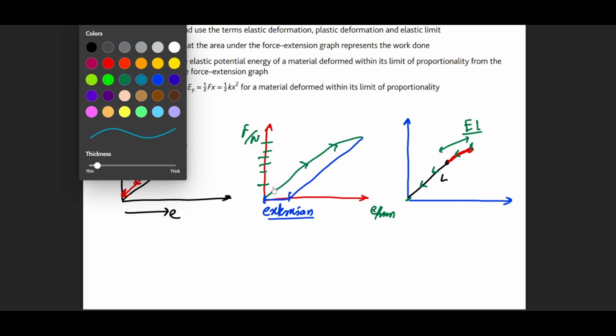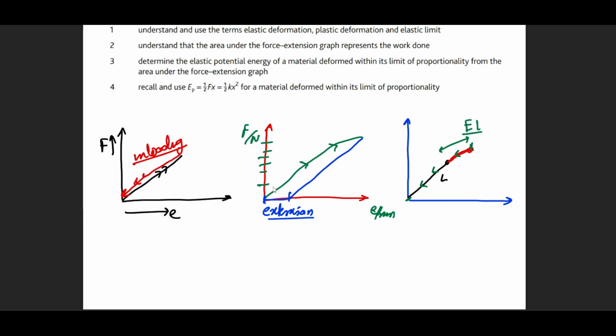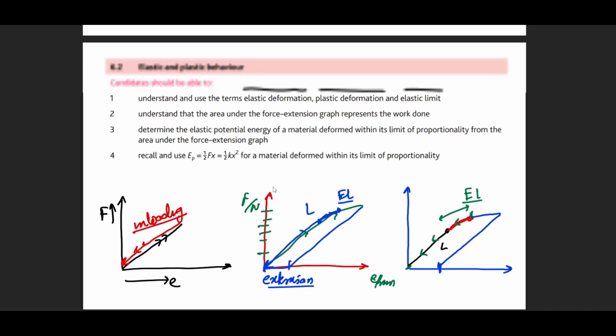After which point is it going to permanently get deformed, right? So even here, this could be the limit of proportionality and this could be the elastic limit. Although this is curved, it could still come back to the original shape. Beyond that, it will be unable to do so, because in these circumstances, whatever strength the metal has, it has already shown that. And if you still pursue by increasing the force, it will then be permanently deformed and be unable to come back. Okay. All right.